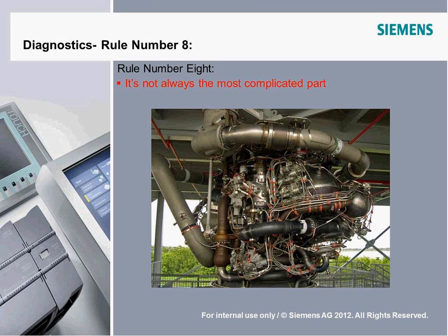Those of you that know the difference know that 4 to 20 milliamp modules, when they're off, still put out a signal. They're trying to maintain a 4 milliamp level, and 4 milliamps is zero. It's off, no pumping. But when you add that into a system that's expecting a 0 to 10 volt signal, if it's hooked up to a high impedance input, that 4 milliamps can go over 10 volts. So every time they turned this thing on, it was blowing up, and it was kind of a mess. I got them to disconnect their hydraulic pump from the motor, and we were indicating the problem, and we saw every time it came on, even if the PLC wasn't telling it to go fast, it was going full speed.